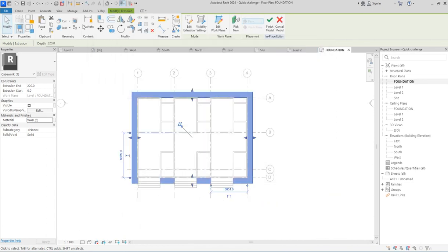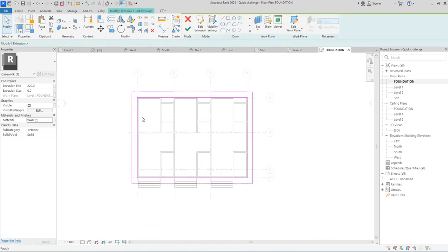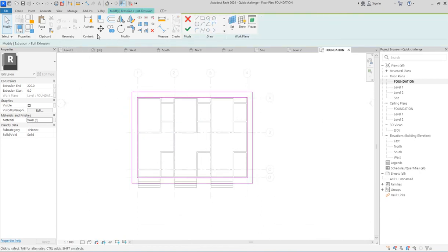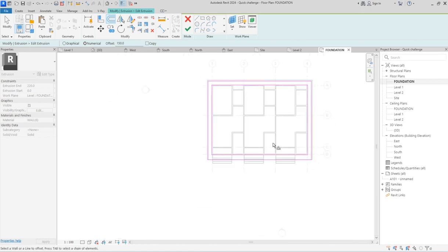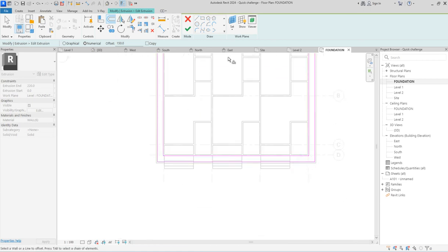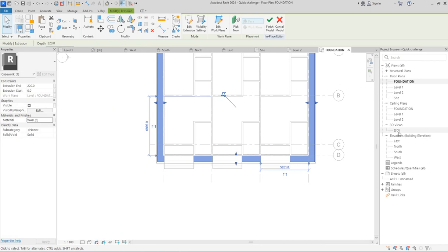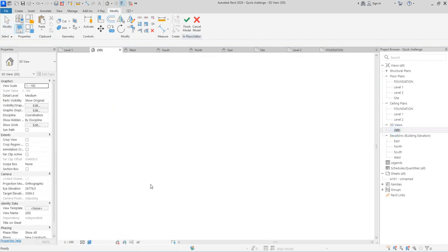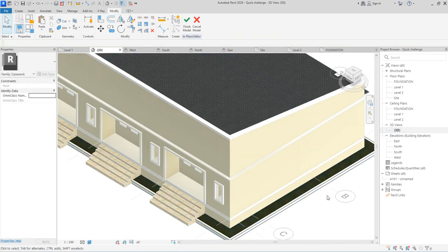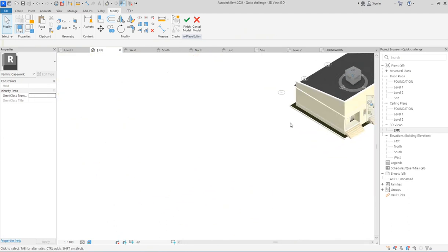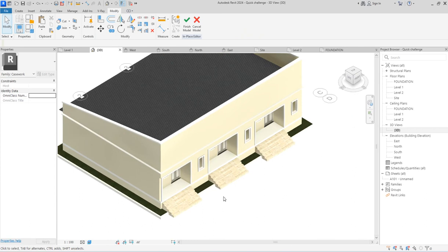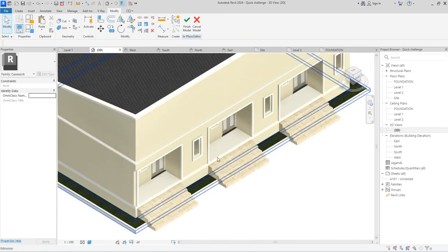So as you have done with that one, now you need to edit it. Offset it here. Where is it? So click here and say offset without copy. 150 is enough. So do that. And all the surroundings. So click finish. After you do that, see it in 3D and this whole project is coming to life. So can you see that things are changing for good and for better? So we're done with this one.